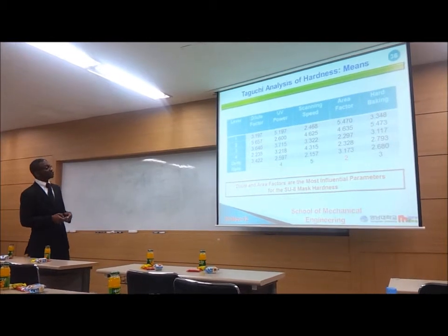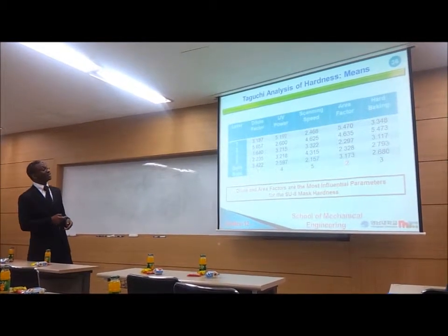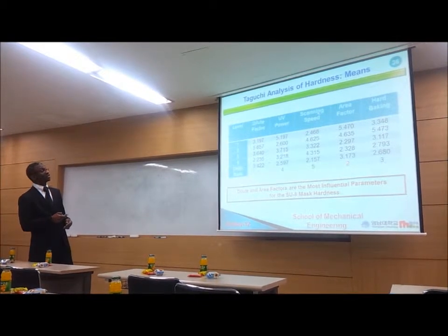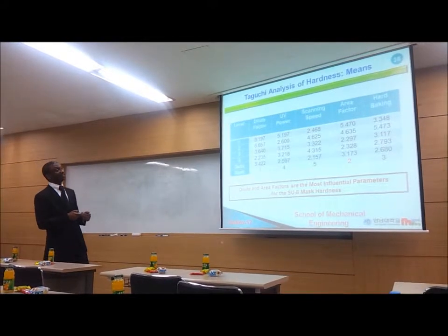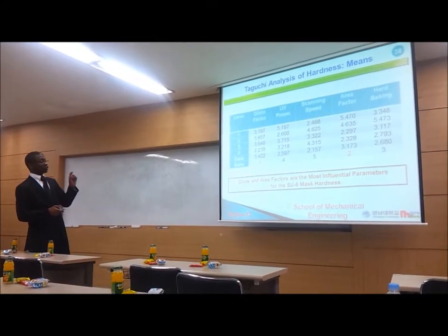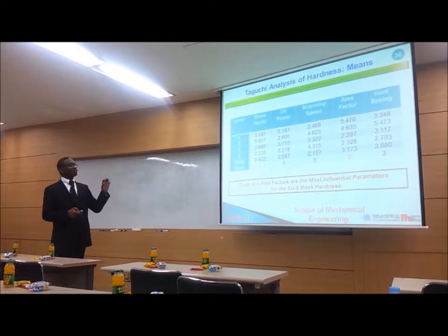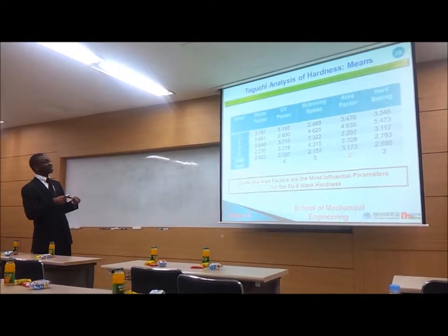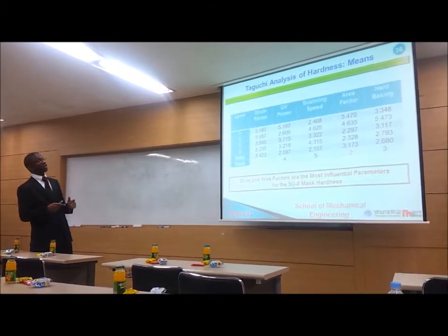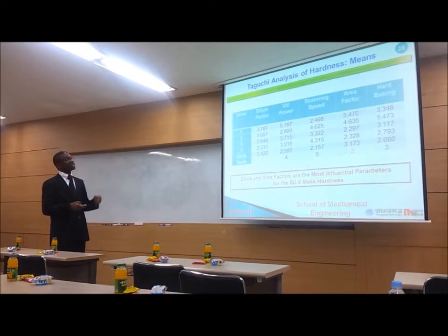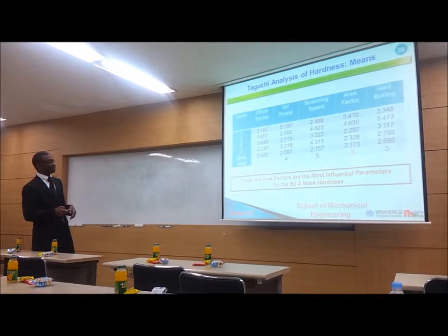Then I started by using the 5 parameters, like a dilution ratio, because I changed the property of the mask. And then I had to consider the power, the scanning speed, and also the area factor. This area factor, I'm defining as the ratio of the beam size to the hatching line. If I am putting the line, the scan path, I have to make sure if I am doing 200 or I am using 100. And again, here I have used hard baking, to set the hard bake time.